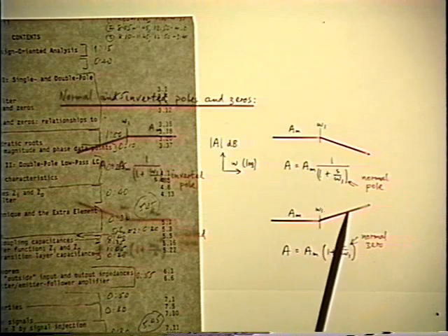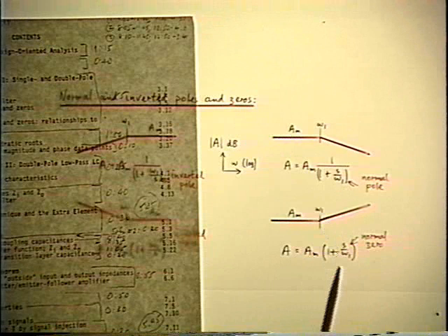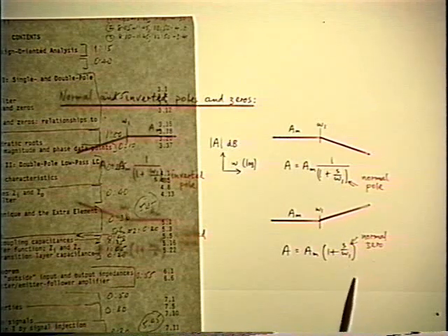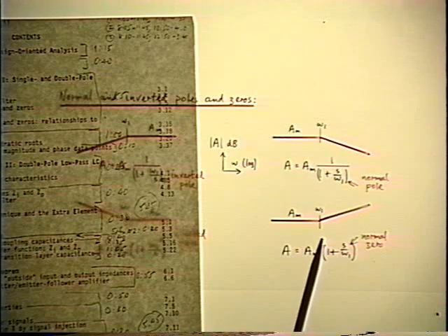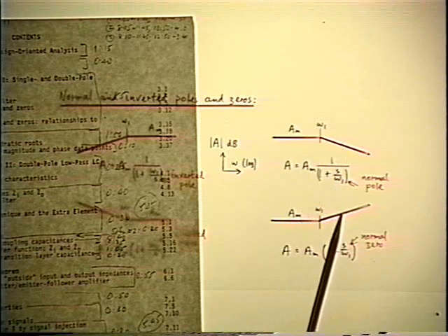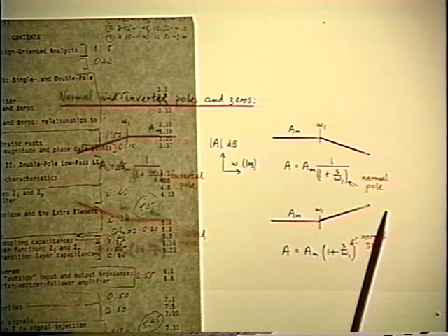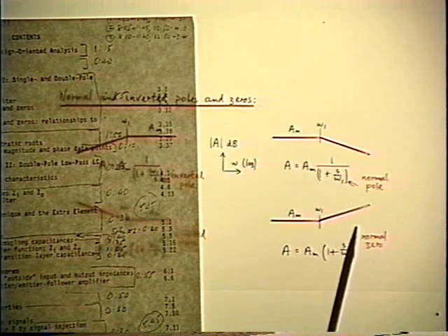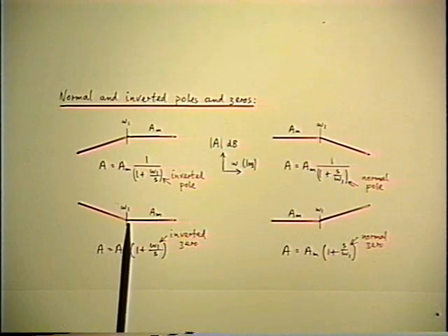And that follows, you see, directly because of the log scale of dB vertically. Because when you move a factor from the denominator to the numerator, that's the same as reversing the sign of the logarithm, because log 1 over x is equal to minus log x. So that's why that geometric relationship exists. Now, that's familiar. You know that relationship between poles and zeros. But the frequency axis is also a log scale. So the same principle applies.